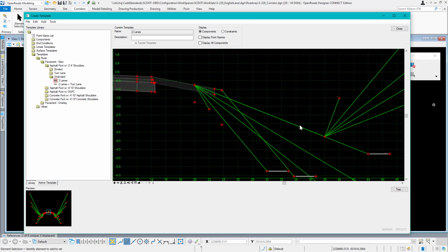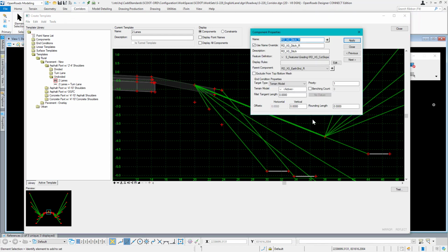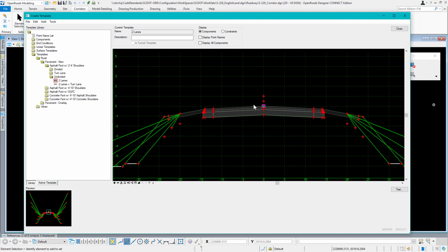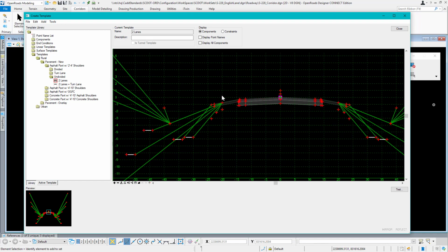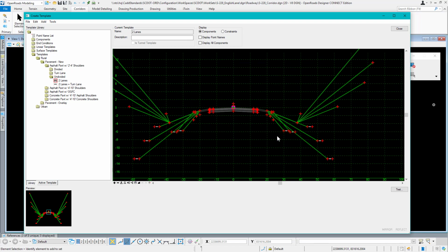So that way it'll come in here and solve, let's say, a ditch first. See, yep, it's lower. The lower the number, the earlier it'll solve it. We'll get into that more later, but just a quick look to show you, we can see our pavement structure, and these green things are called end conditions.